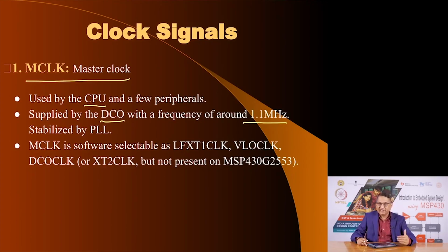but you can select the master clock signal to come from low frequency crystal oscillator, to come from VLO or the DCO, and XT2, that is a high frequency crystal 2, but this option is not available on our microcontroller, this particular microcontroller part.